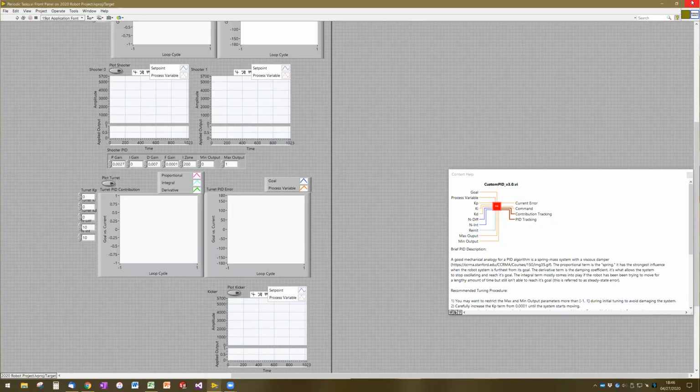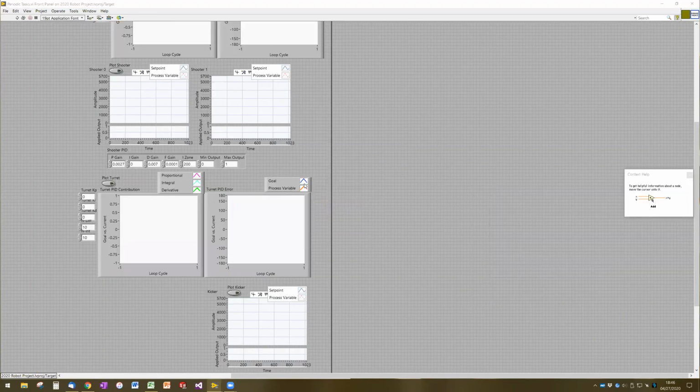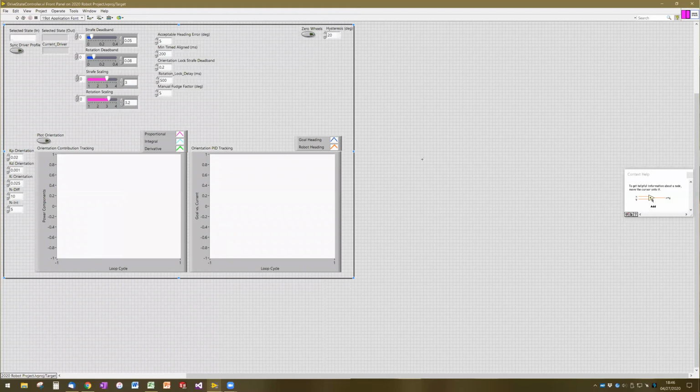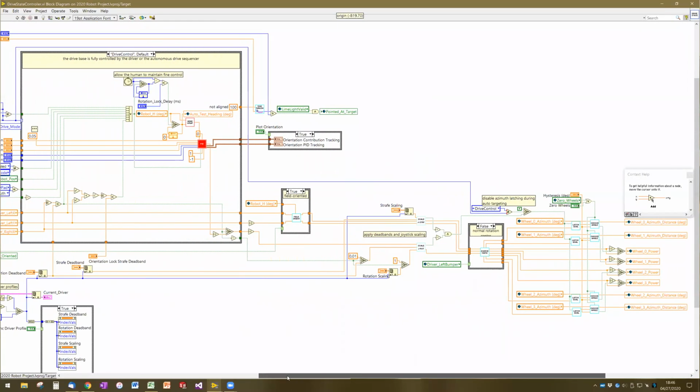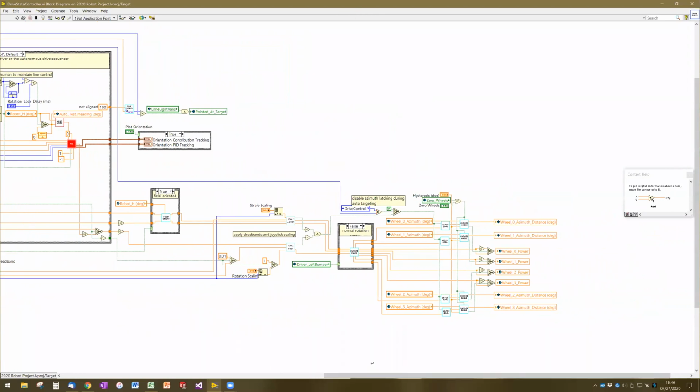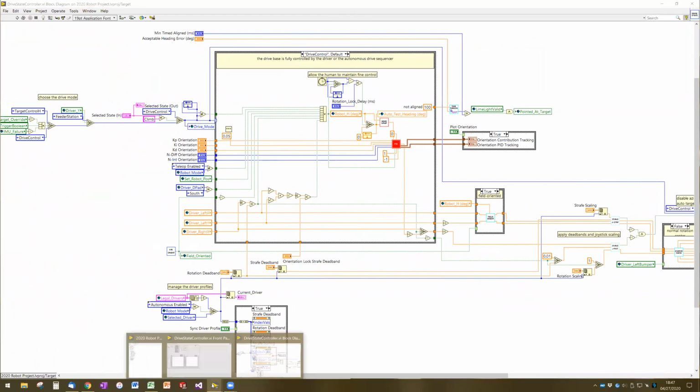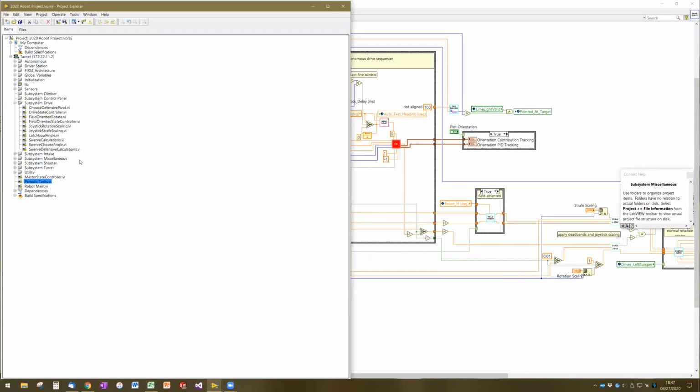Okay. So the next thing that we need to talk about is that we've been working with angles, but the physical sensor on the Swerve module, the azimuth encoder, does not give values in angles. Instead, if you don't do anything special to it, it gives values between 0 and 5 volts. If you do what I'm about to show you, it's going to give a value between 0 and 1. And so we can see where we initialize the azimuth sensor inside of the begin VI.